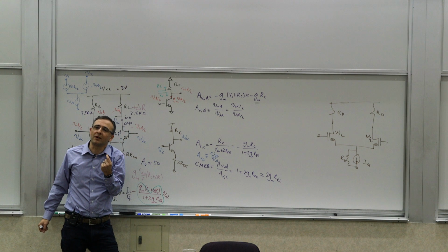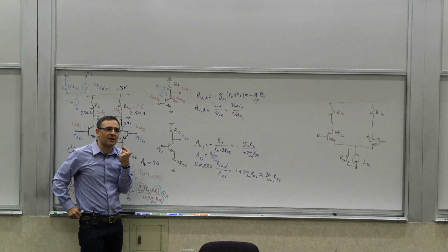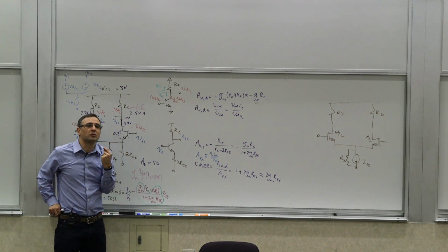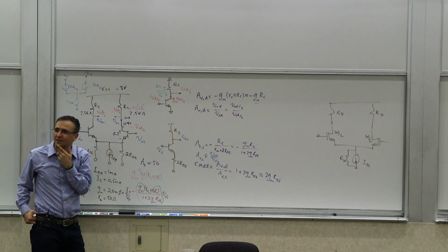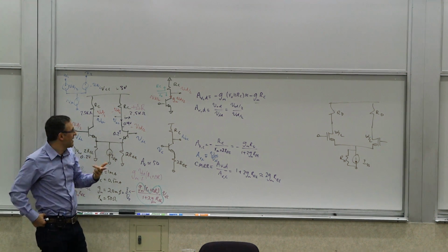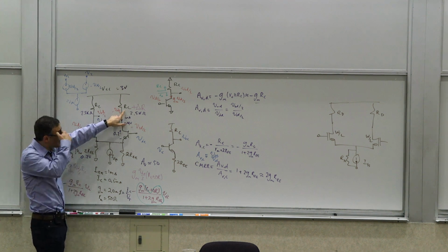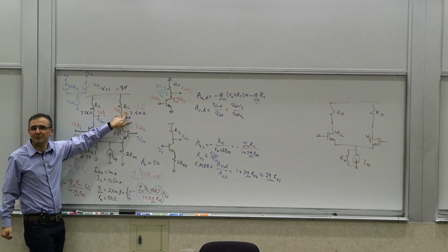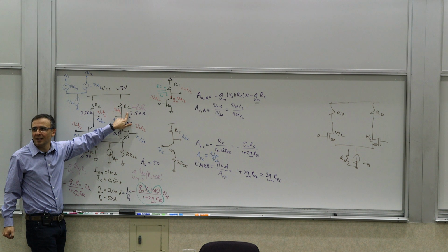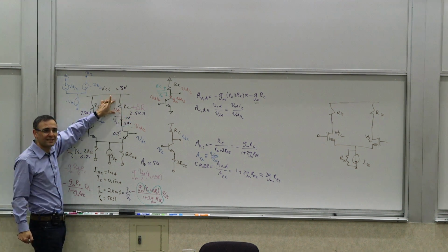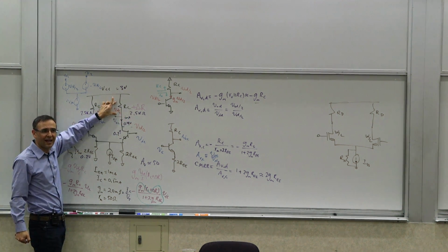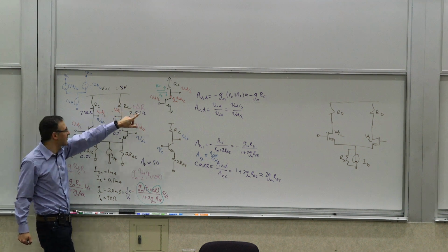Where is this coming from fundamentally, if you think about it? When you use a resistive load. Headroom, correct. And where do headroom limitations come from? There's a direct coupling between the DC and AC behavior of these two things. The DC drop across here is determined by exactly the same parameter as the AC performance gain, which is both RC.